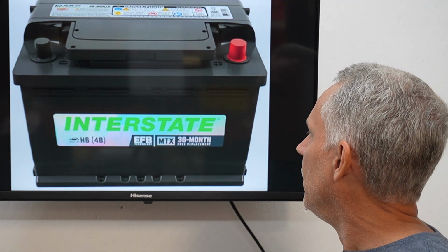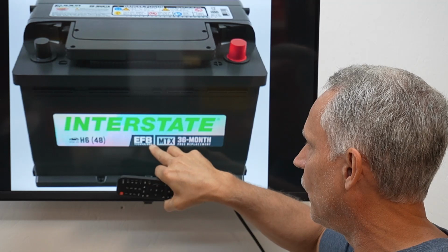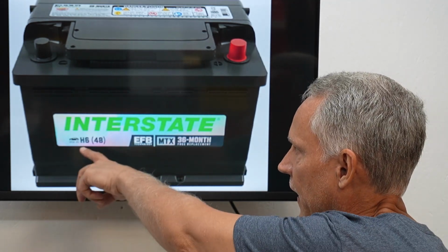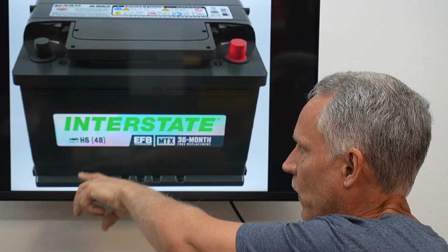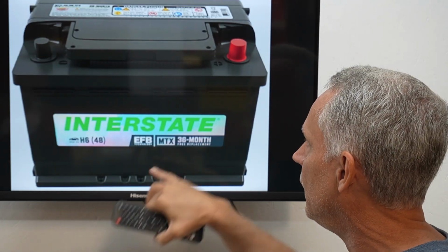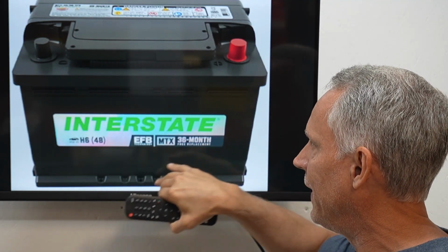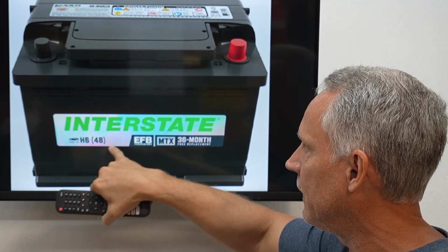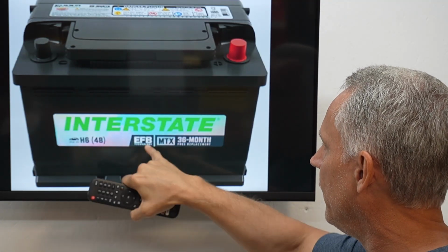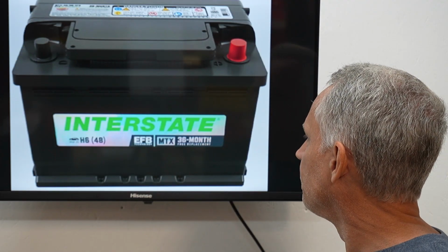Okay, same thing. This battery, like I was saying before, see how it says EFB, Enhanced Flooded Battery? This is for start-stop vehicles. And you'll see right here CH6 and 48. That's a group 48 battery with a DIN group of H6. So probably designed for like a German vehicle, Audi, VW, Mercedes-Benz, which would have an H6 designate, but the Group 48 battery does cross-reference. That's what this means right here. EFB, enhanced flooded battery, like I said, probably for a start-stop type vehicle.